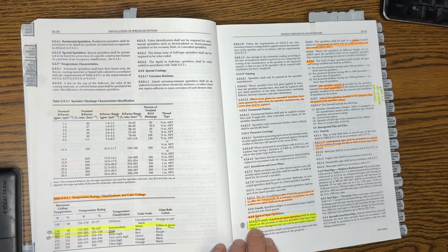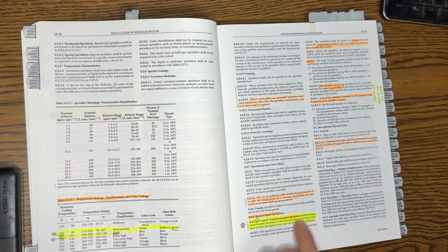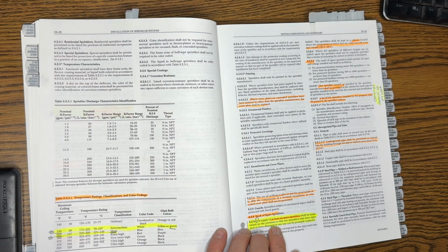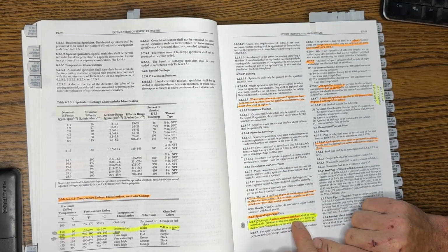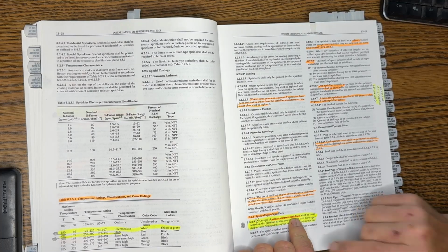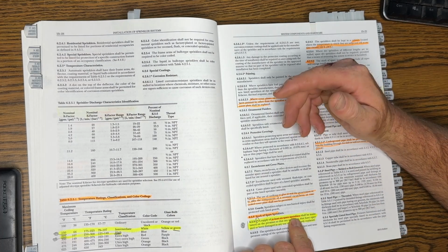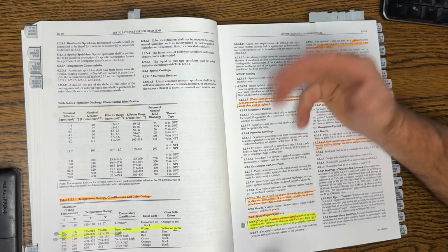Let's see. Next question was 6291. A supply of at least 6 spare sprinklers shall be maintained on the premises. So here's what it says. What is the minimum number of spare sprinkler heads required to be stocked for a building with 240 heads and 7 different types? Okay? This is going to nail you, folks. Because it says right here 6 spare sprinklers. But in the question that ICC gave you, they said there was a total of 240 heads in the system with 7 different types of sprinkler heads. And what the heck do you do?